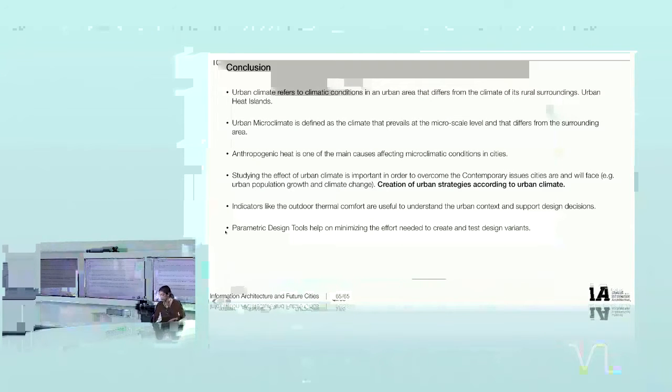Yeah, I think the video doesn't work, but here we used evolutionary design algorithms, and in this particular case it was the genetic algorithm, and it was used to find the most adequate point in this urban block that can meet different criteria of shading. So we had the winter shading and the summer shading, and then the idea was, according to predefined criteria, to find the optimum place in this urban space.